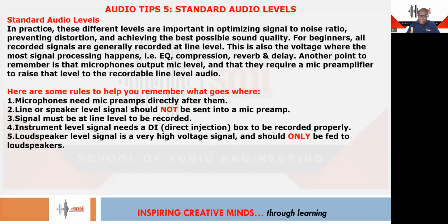Why? Now, a DI box does 2 things. One, the first job of a DI box is impedance matching. And the second one is distribution. But impedance matching is this. When we talk about bringing the level down, all musical instruments like guitar, when you connect them to a DI box, it brings that level down to a mic level. And that is the reason why you can actually plug them directly to what? To a stage box with mic input.